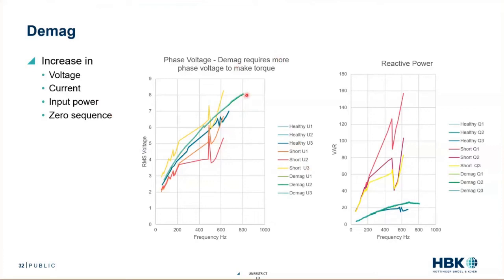Why an increase on input voltage? Well, the flux on my rotor is smaller, so I need to provide more voltage on my stator, more voltage from my inverter, to provide that same flux to get that same torque output. So we see, this is subtle, but not that subtle. We can start to see this failure creeping up. This is really cool. We can see that little tiny failure, and I'm pretty sure this was asynchronous, but we see that. That's statistically notable.